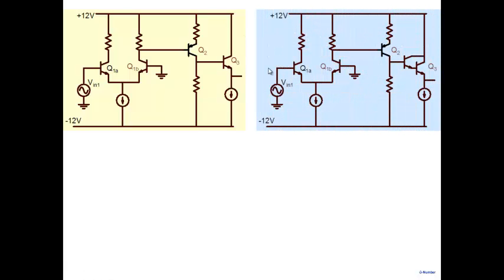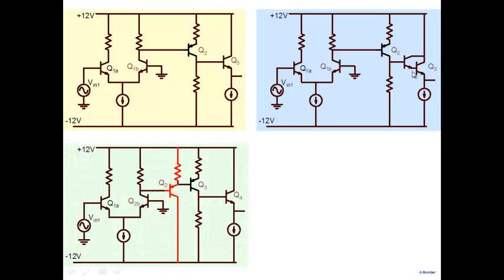In our effort to get lower output resistance, we had used this, and I sort of abandoned it and went for this particular stage. But that doesn't mean this cannot work. If you go ahead and optimize, I have not looked at it, but it's quite possible that you'll be able to get 1000 gain, lower output resistance, and input resistance through this stage.